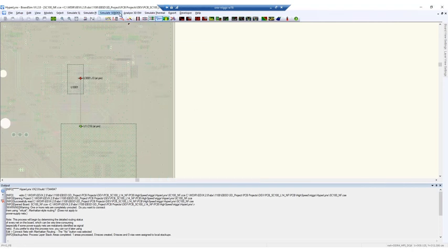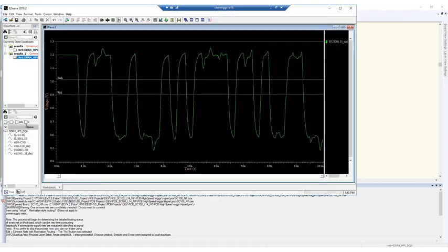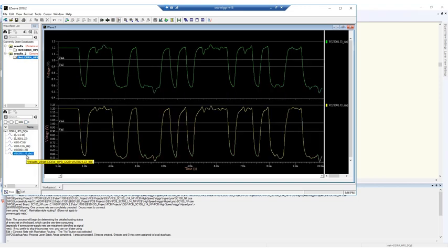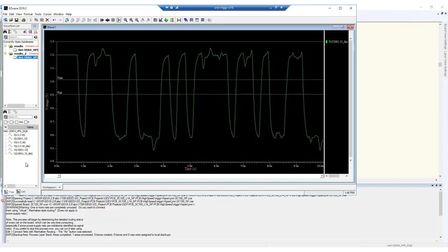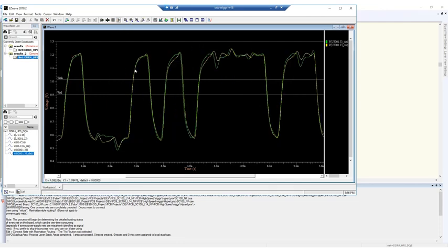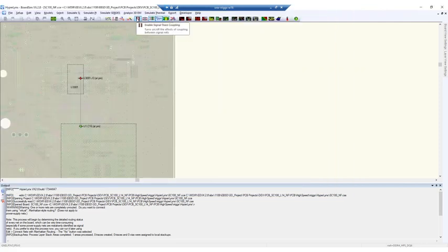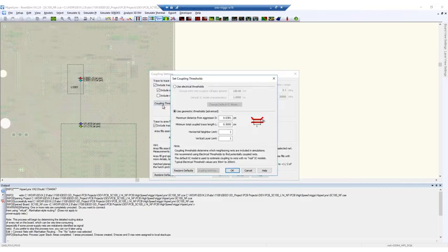So we are spending this time and effort to make a more realistic model of the board behavior before fabrication, and if we pass these checks, we can go into manufacturing with a greater peace of mind. If the board fails with ideal planes and no assumptions for PDN effects, noise, etc., then we know we have big problems. Since we have passed all the other simulations so far, now it's time to make sure it passes a more robust version of our board.